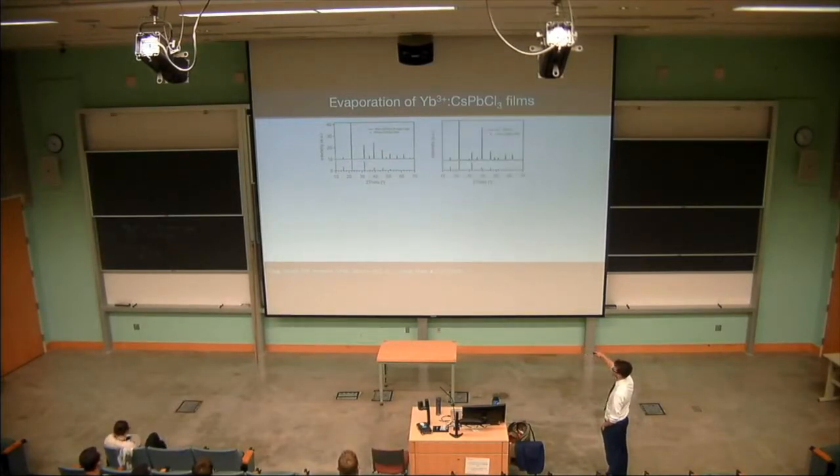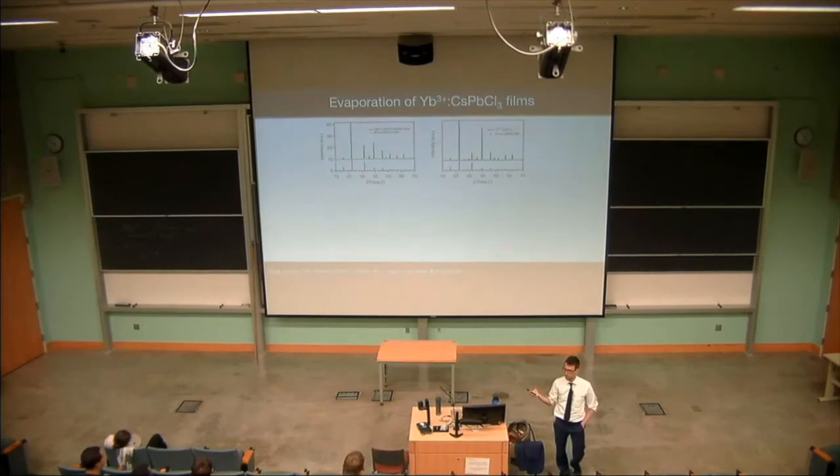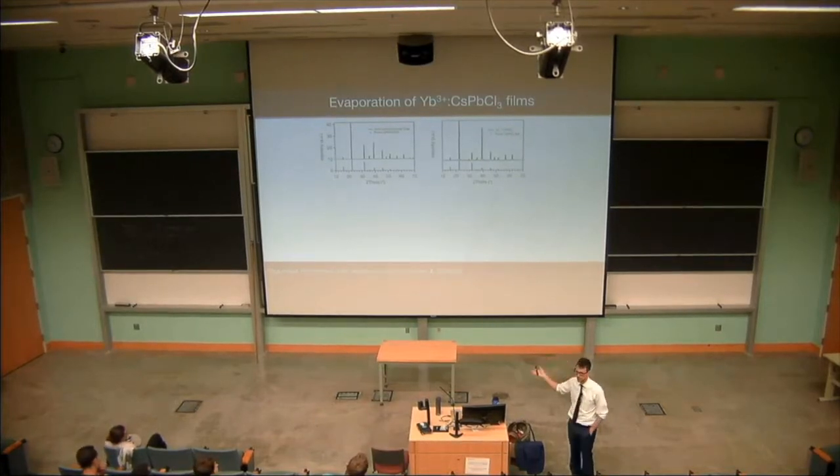And if we evaporate it onto a film and do XRD, astoundingly, we seem to form all of the right peaks. That means taking just this powder, this single source material, and heating it up rapidly, all of the phase diagram is appropriate, apparently, that whenever it evaporates and hits the substrate, the vapor pressure forms the right material.